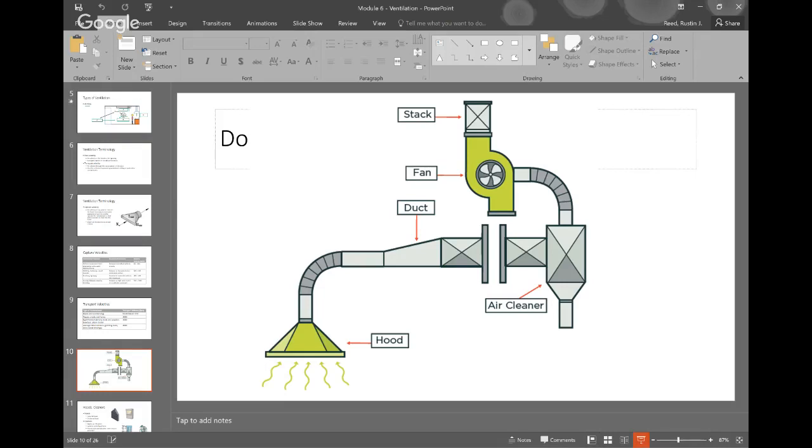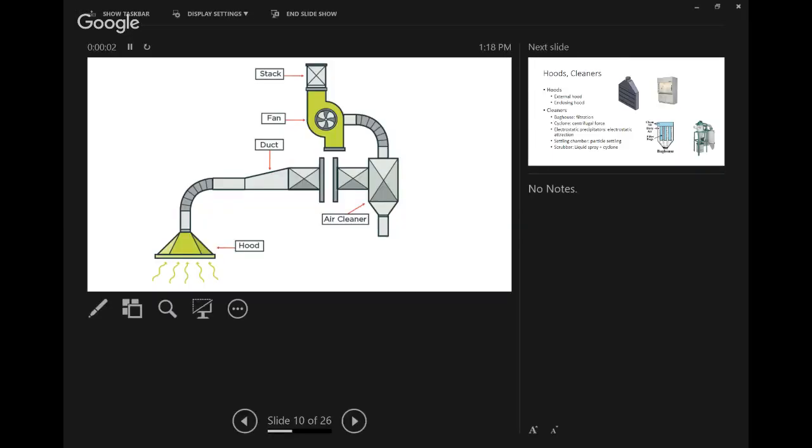Real quick, after spring break, we'll talk about the theory part of gases and vapors. It's not a lot, but I'm just going to lump it with the respiratory protection lecture. But if you want to clean gases and vapors from an airstream, there are different ways you have to do it, because a fabric filter is not going to stop CO2 or CO or any gas. It's just going to keep going.